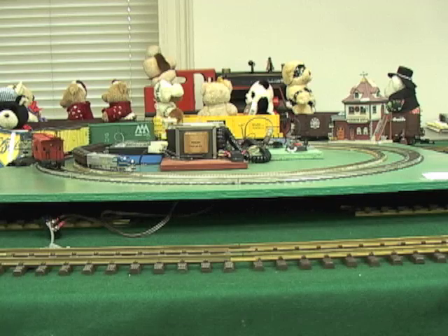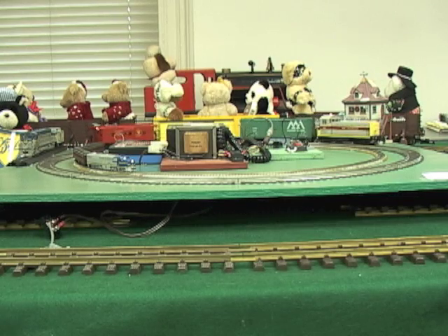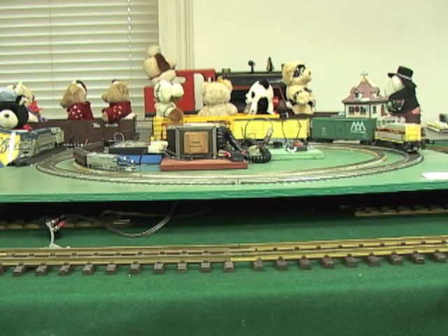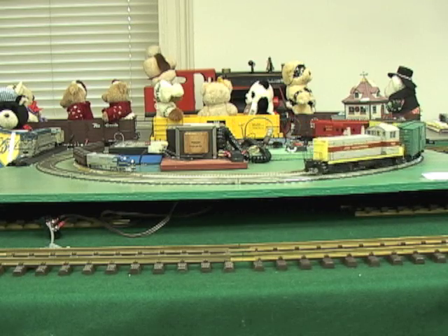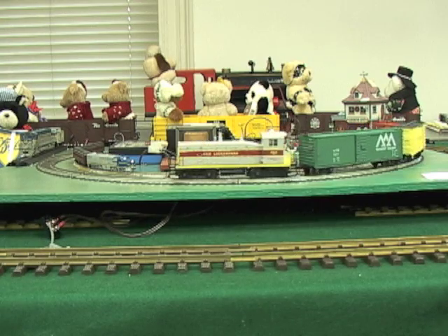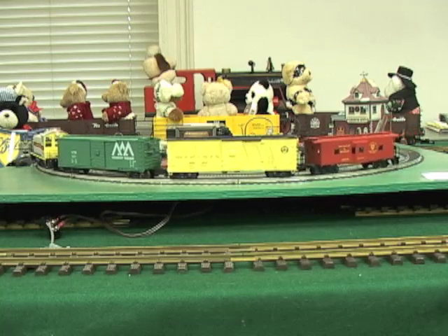As I started to mention before, you need to put a delay statement in so that it travels around a couple times. If there was no delay statement, it would stop the next time it came to the electric eye before it really got started. So I put a delay statement in. It makes it travel 2 or 3 times around the loop.